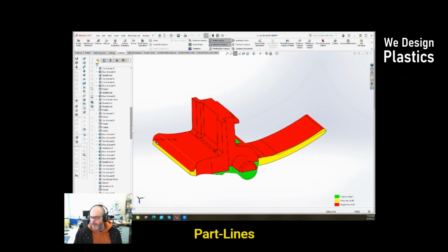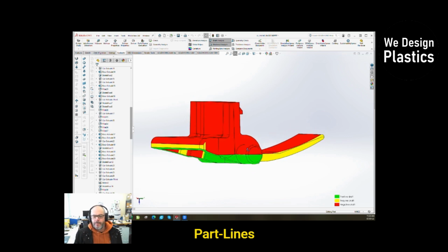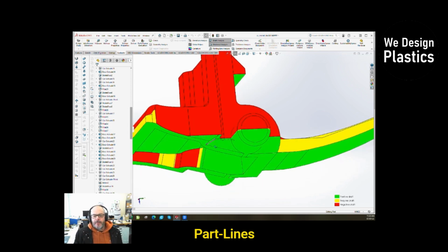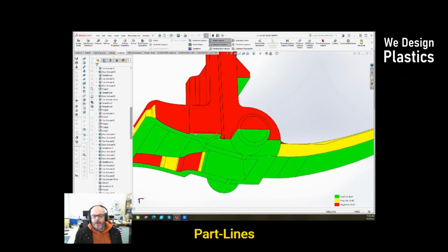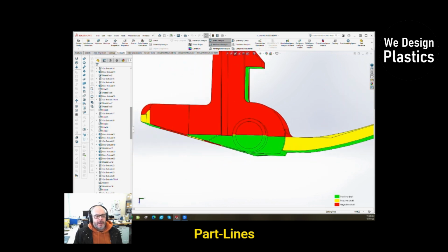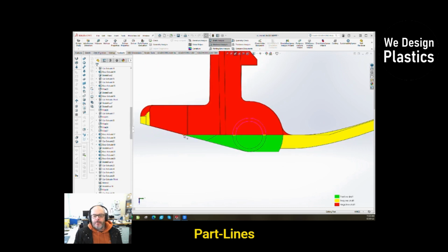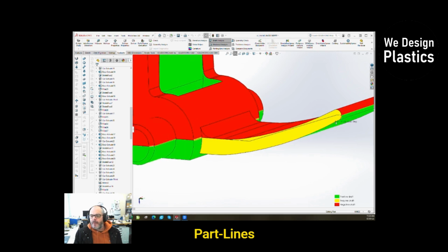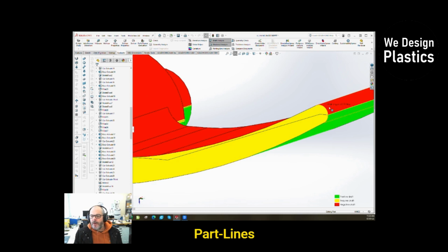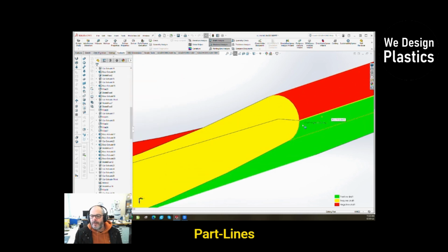A defined part line. So you can see this part here has got this defined part line. That's all sort of nice and horizontal through here. Then to create this spring finger, there's an angled part line and then another horizontal to get a nice part at the right point of this radius so that we don't end up with an undercut there either.